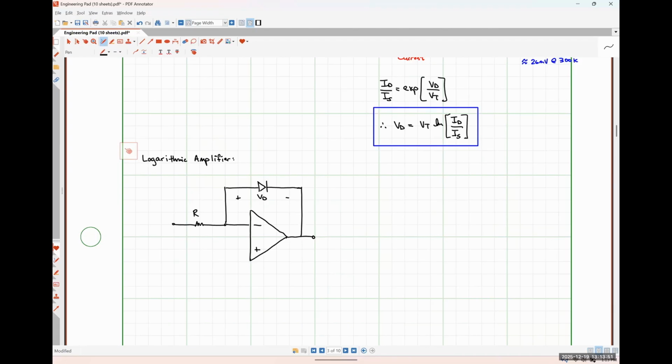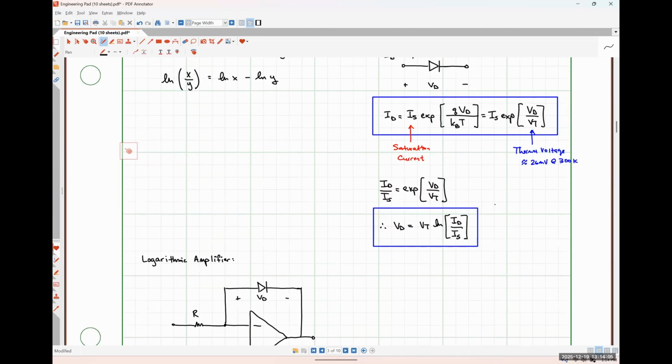Okay? The line up and down essentially acts like a wall. Sure, that's one way to think about it. I always thought about it as the line is the negative terminal. That's how I remember it. But yeah. So if we look at this current relationship here, right? We need VD to be much, I say much, but not a whole hell of a lot larger than VT. Our current is going to grow exponentially.